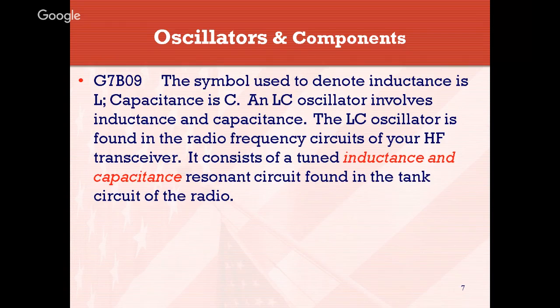And sometimes these do get out of tune. Maybe the crystal, as it ages, might drift a little bit, and so the inductors and the capacitors have adjustment capability to allow you to retune to get back on frequency. Your dial may be a little bit off, and sometimes these circuits can be tuned to basically put your radio transmitter and receiver back into proper alignment.